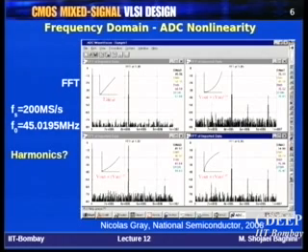Suppose you have 45 megahertz, so you expect 2F0, 3F0, 4F0. But practically you have a sampling rate, and eventually it is a repeated spectrum. So with 45, your second harmonic will be around 90 megahertz, but the third will be 135, which is beyond fs by 2.